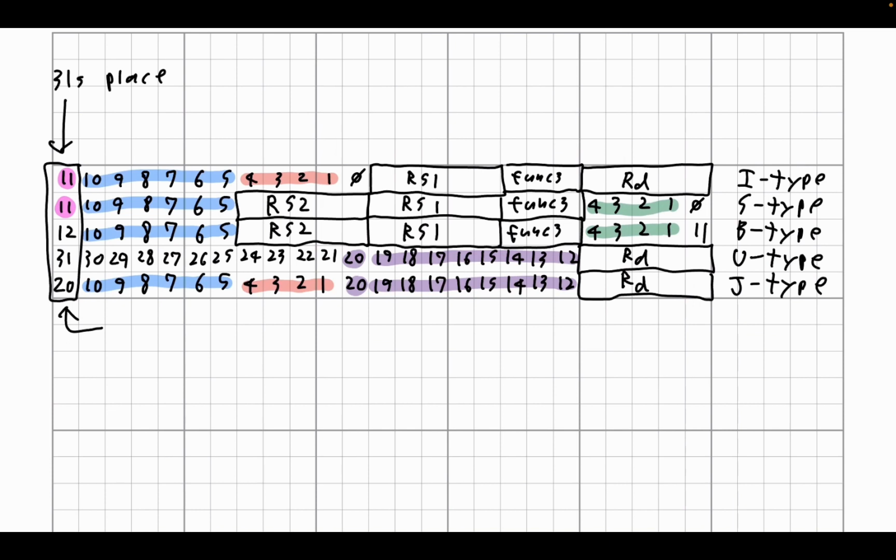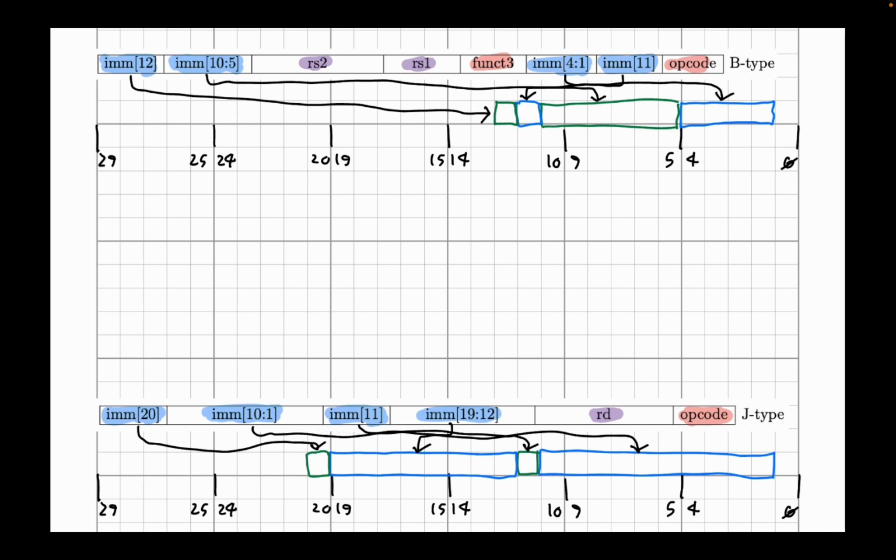It does make things a bit more complicated, but again, fan out is potentially the weakest link in the entire process. We really would like to do something to minimize the adverse effects of that fan out if we can, and this is not too heavy of a price to pay. So that is why RISC-V does this weird bit swiveling stuff.